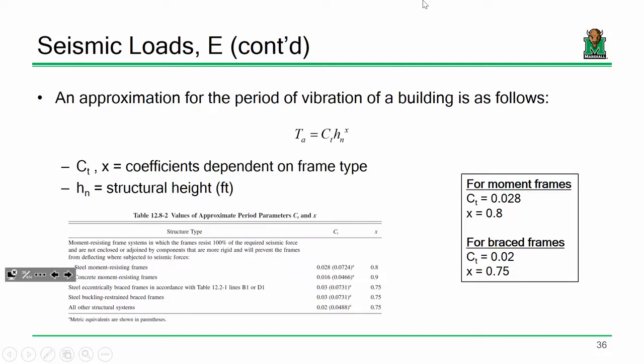Luckily for the regular old design engineer, there are some very basic models that we can use to compute what's called the building's period. The building's period is just how long it takes for the building to go through a given cycle. So if here's the building, it vibrates and comes back. However long that cycle of vibration takes, that's the building's period of vibration. Sound reasonable?